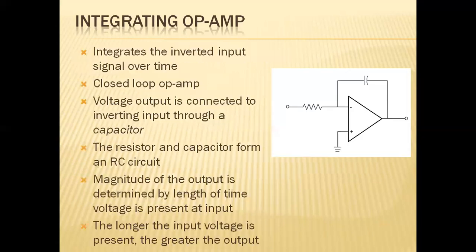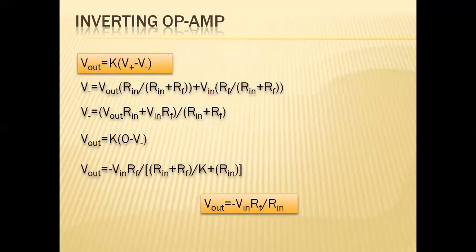as we'll be seeing diagrammatically here. This is a negative terminal, and this is considered an inverting amplifier. When this is changed to the positive terminal, it is considered a non-inverting amplifier. In the case of the inverting amplifier, the output voltage will be obtained based upon the negative ratio of the feedback resistor to the input resistance.